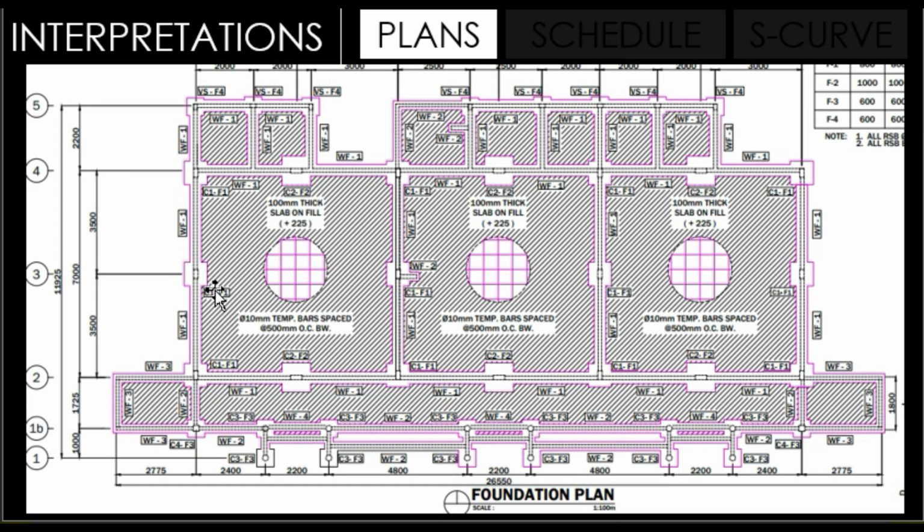Next, foundation plan. It is a top view providing project managers with the number of units of columns and footings. It also shows the area of slab, the location of the structural elements like columns, wall footings. We also have the dimensions such as the running lengths of wall footings and grade beams if there is, but there's no grade beam here.